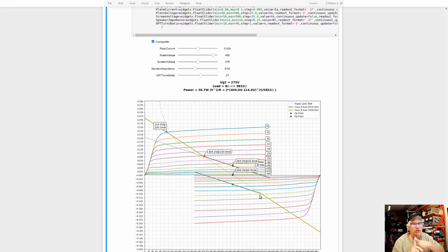You've got to have matched power, matched tubes, you have to have matched biasing on those tubes, and you have to have a transformer wound such that the DC resistance of both of the legs of the output transformer are equal. And getting a transformer wound that way is more expensive than just winding it so that one leg is a little higher than the other. The reason is the way that they put the wire on the spool. They have to wind it simultaneously.